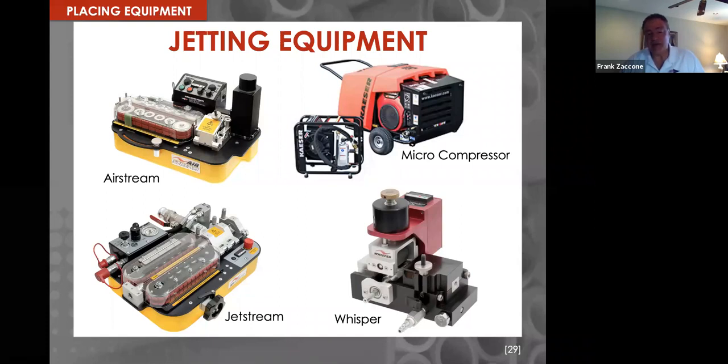That's a drill-driven unit. It's that unit right down on the bottom right, and that's what we call our Whisper. That's ideal for runs for fiber to the home, where they're going maybe 1,000, 2,000 feet. And it's a pretty small unit. The installer may have it in his truck or whatever, just pull it out for those short runs. And this is ideal for that. So it's belt driven. Well, actually, this is roller driven. You've got a rubber roller there, but then it's air assisted. So you can plug a compressor into it. And if your distances are longer, then it is air assisted, so you can use that for air as well.